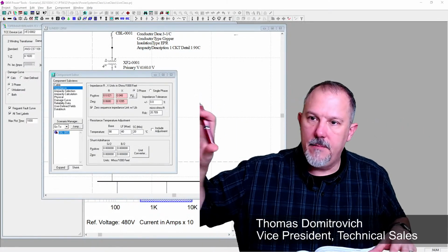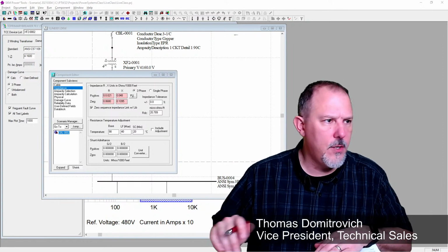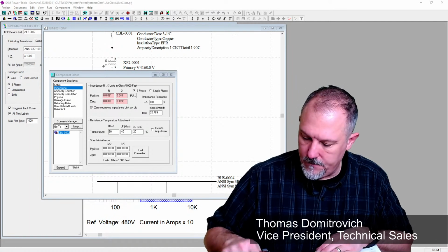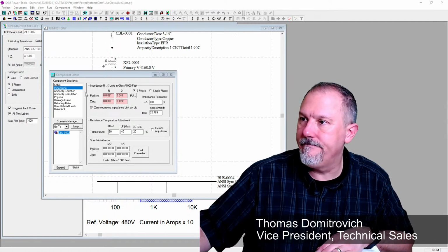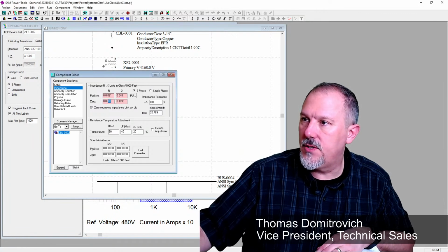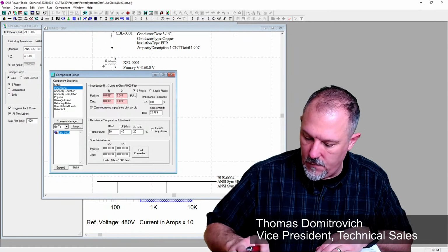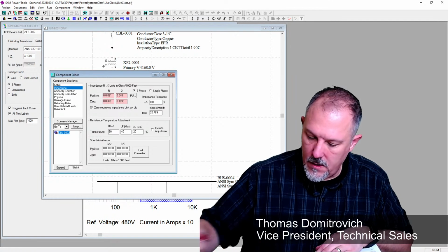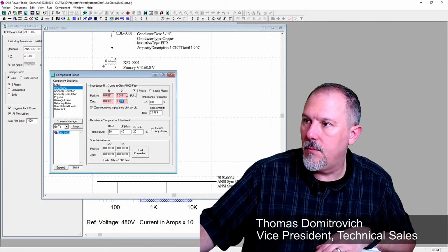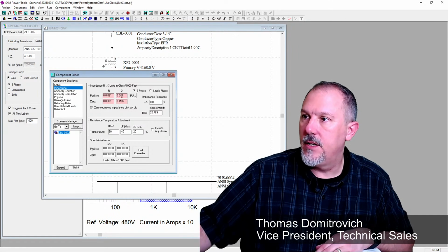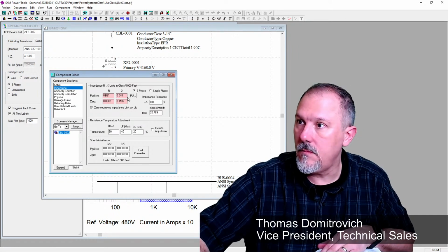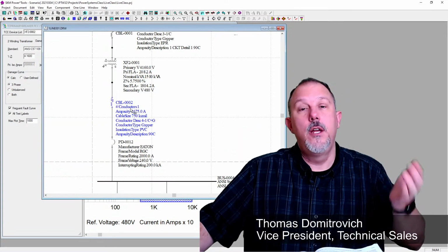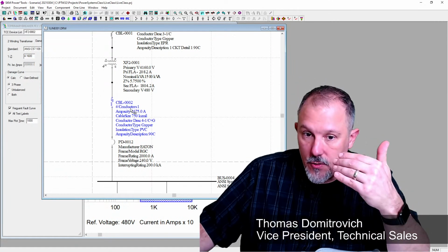So my library is what I'm doing over here. 3.1515 times 0.021, and that's 0.0662. And then 0.048 times 2.4617, and that's 0.1182. So that covers our positive and zero sequence, and we're going to need the zero sequence again to do our ground fault currents.